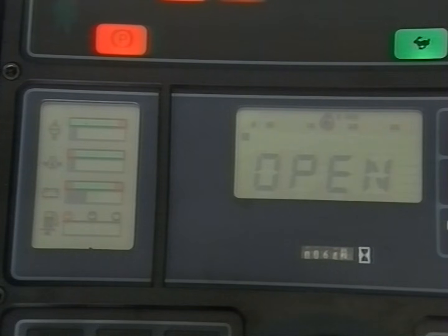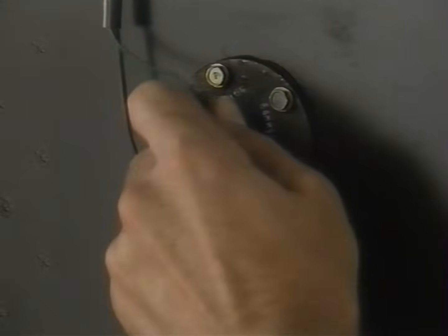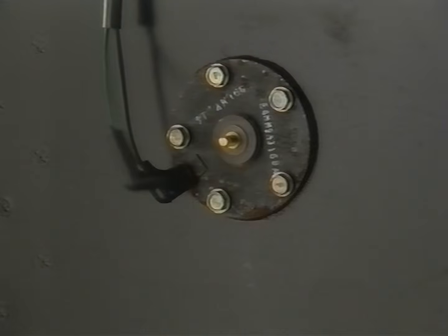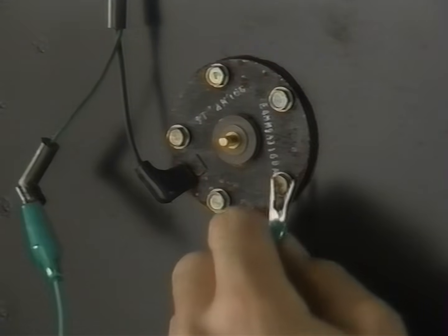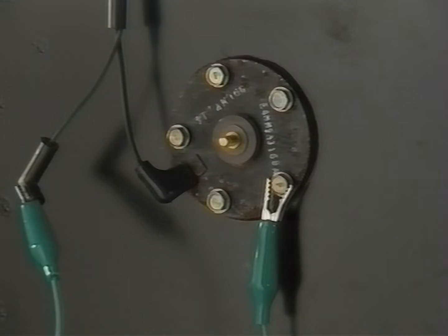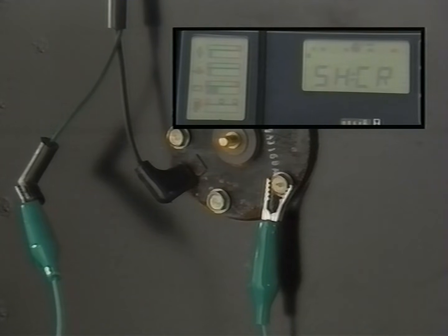With these precautions out of the way, let's look at troubleshooting a concern indicated by the self-diagnostics of the electronic instrument panel. Suppose, for example, that the instrument panel is indicating an open in the fuel tank sender circuit. The first step in troubleshooting is to check the connection at the fuel tank sender. If this is all right, remove the sender wire to the EIP and connect it to a good ground while observing the EIP display. If the EIP indicates a short circuit when the key is turned to the on position, it indicates the circuit is all right up to the sender and that the instrument panel self-diagnostics are accurate.